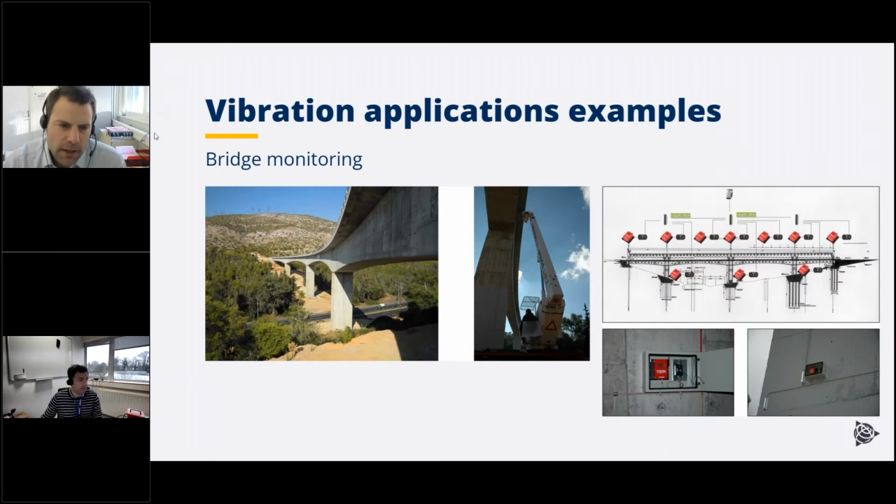And last example, I think, is a bridge monitoring in Greece. In this case, they put these sensors that you see on the right, and the power option here was interesting because it was PoE, so you can connect these devices using PoE, meaning that you have only one cable to get Ethernet communication for remote access and also the powering options, and then you push the data to any type of platform. Could be T4D in this case, with several sensors plugged in one software solution.